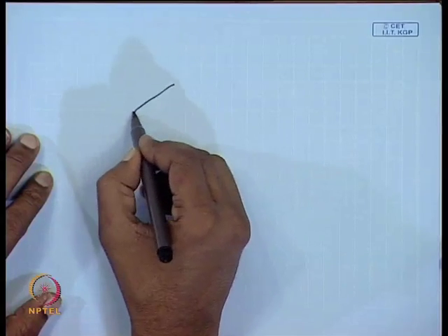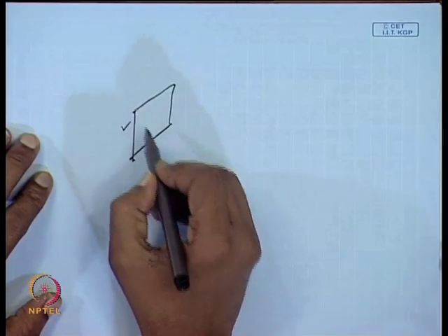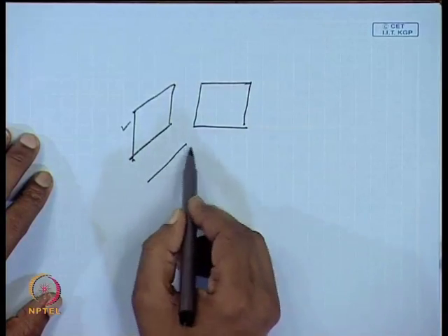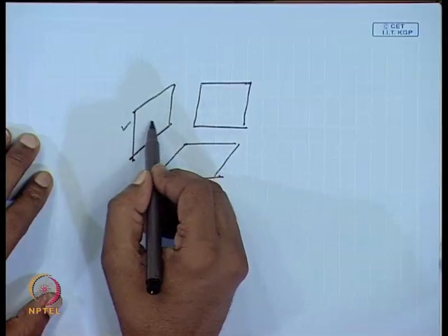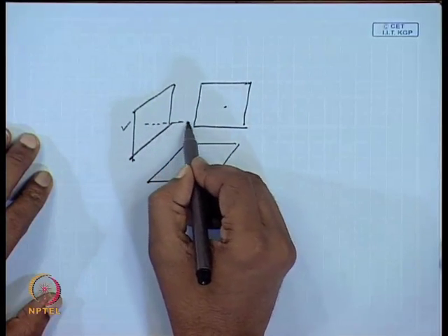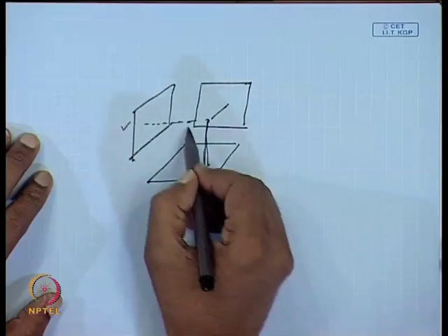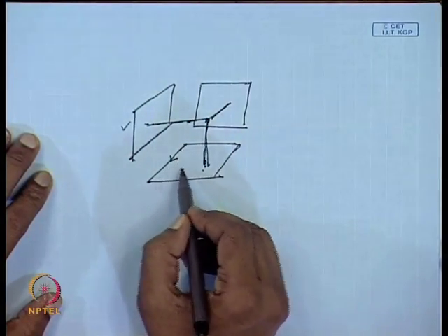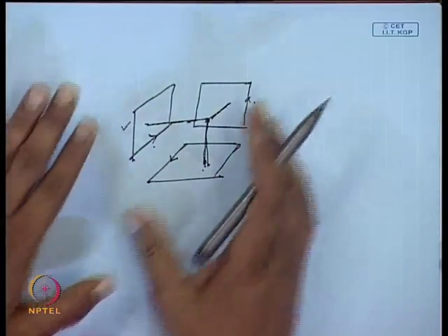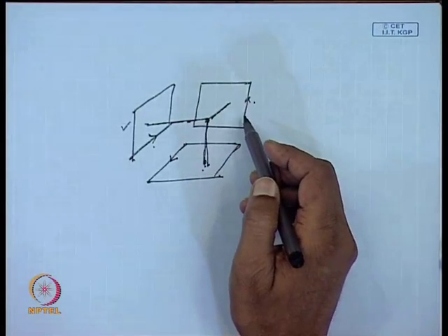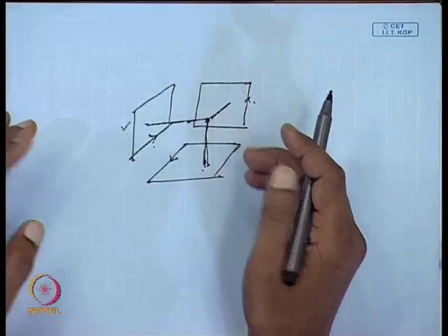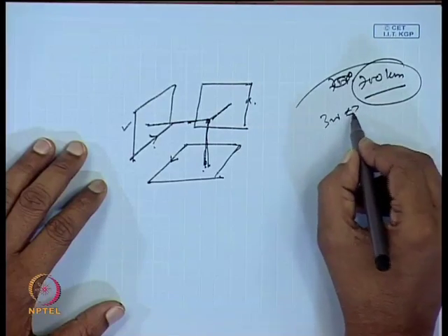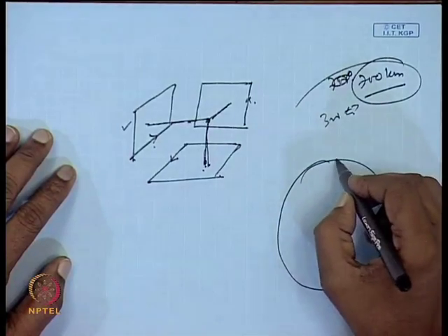In the magnetic actuators we have 3 coils. This is one current carrying coil, another current carrying coil will be perpendicular to this, and another will be lying like this. So these are in 3 different planes, and we can assume that the center is here. This is one face of the first coil, this is the face of the second coil, and this is the face of the third coil, and these wires carry the current. If this is put on board the satellite, and the satellite is at low altitude, 300 to 700 kilometers, then as we go up, the magnetic field of the earth dies out fast.